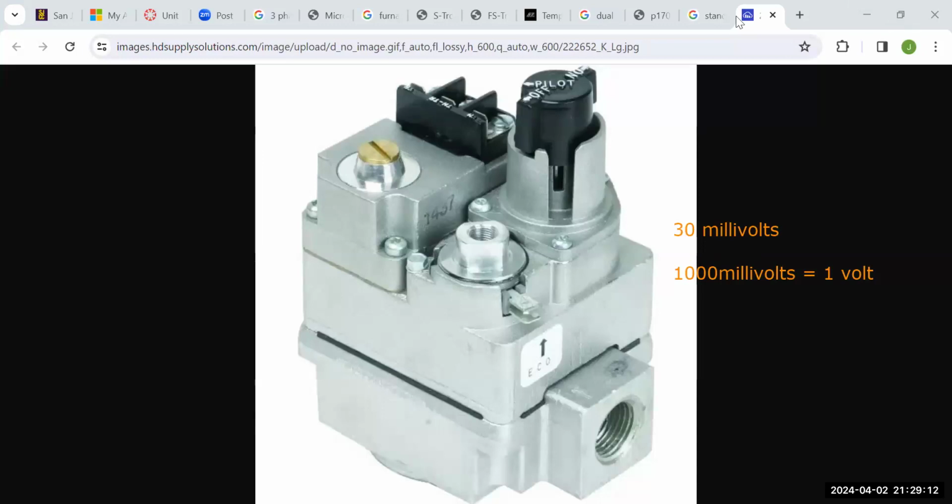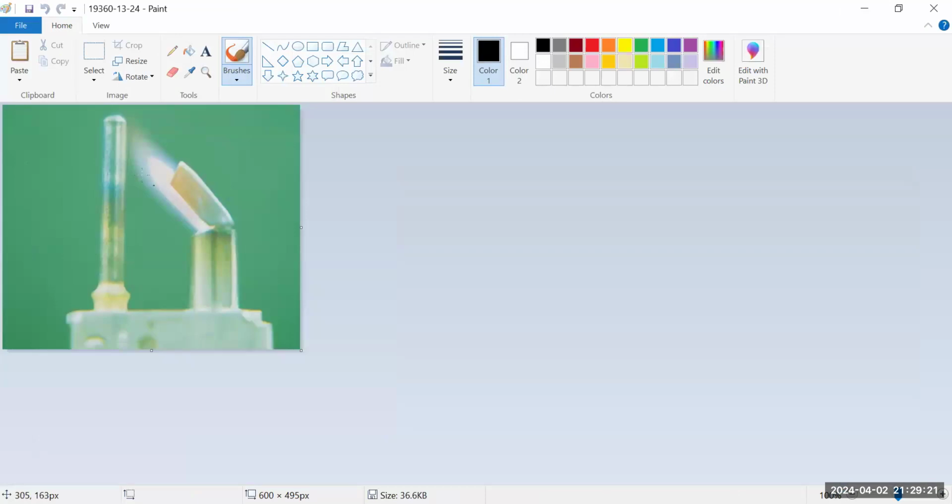So once you get in there and you light the pilot, you should have a nice pilot flame on the thermocouple. Well, that thermocouple is going to take 30 seconds to get smoking hot.